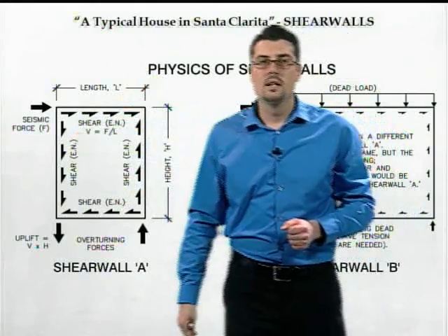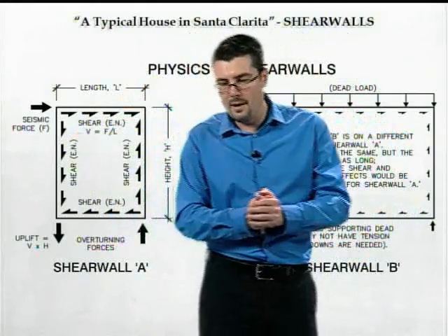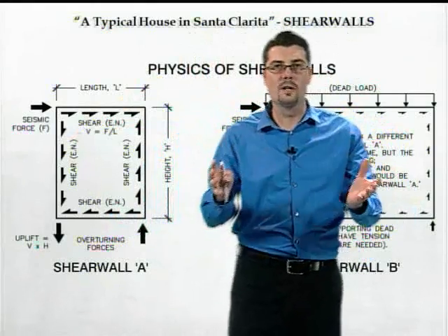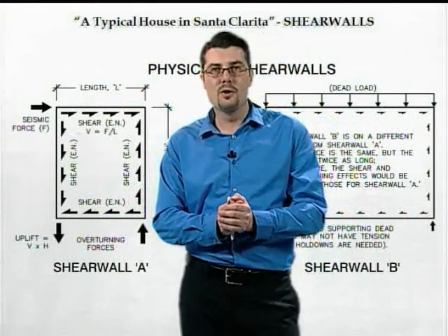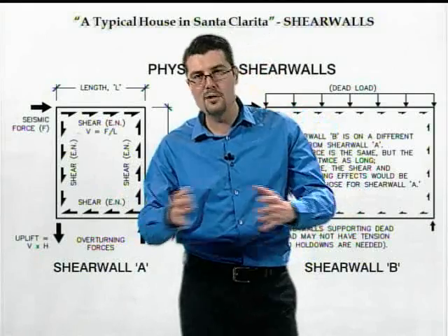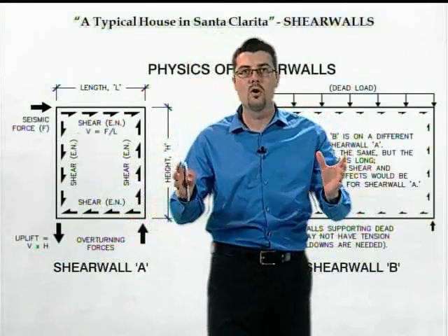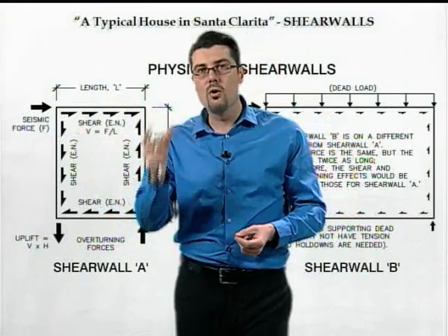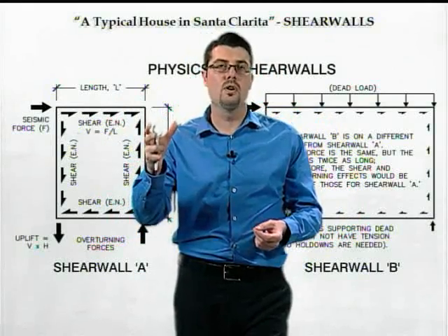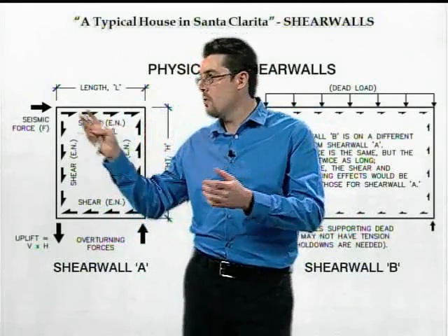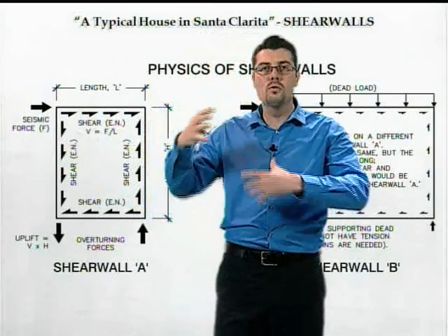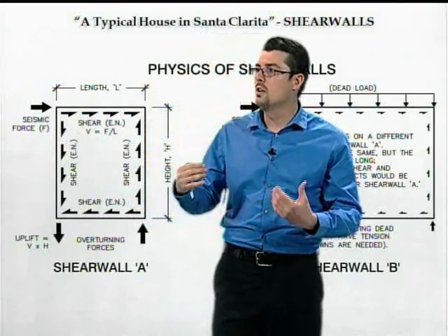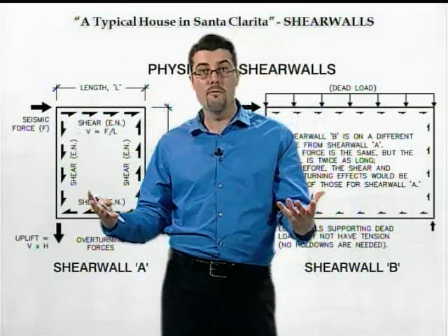And if you're a builder and you've ever cut a hole in a shear wall, you'll know that inspectors don't like that and engineers don't like that. A hole in a beam can be done if done properly, not a big deal. But a hole in a shear wall or altering a shear wall is a really big deal, and it's for this reason. You've got uniform force acting through a shear wall. And of course, we call the force shear force.